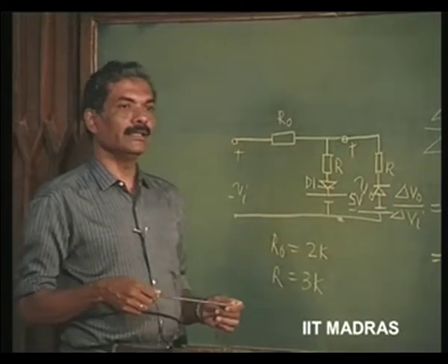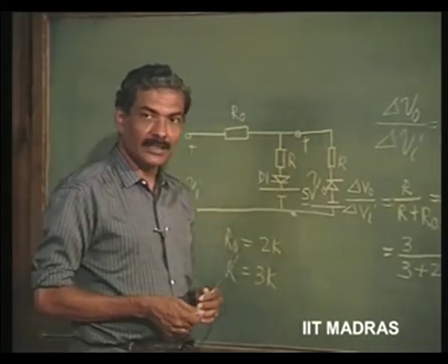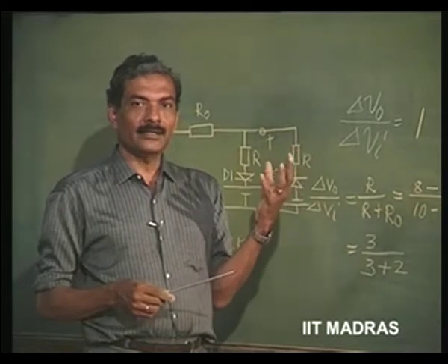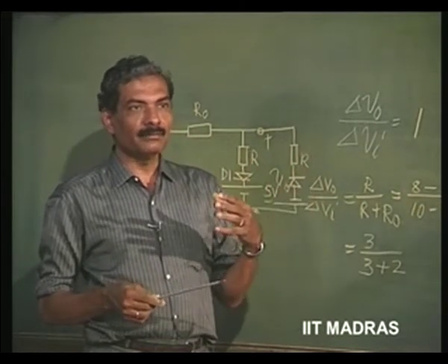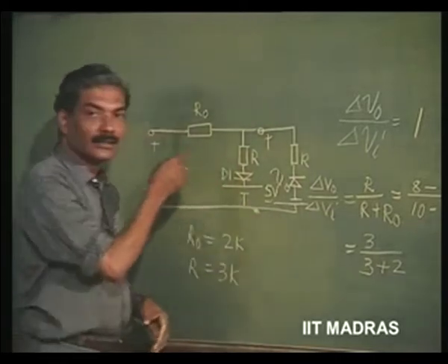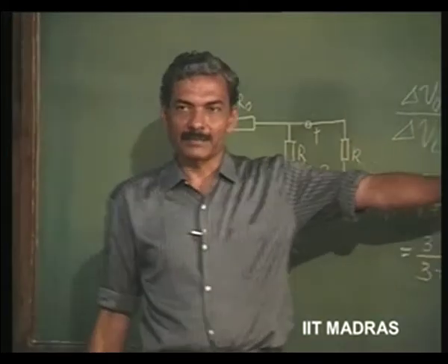This is the technique adopted even in integrated circuit function generators, which very easily can generate square wave and triangular wave, and the sine wave gets generated using what is called a diode function generator, with a lot more approximation than what has been done here.